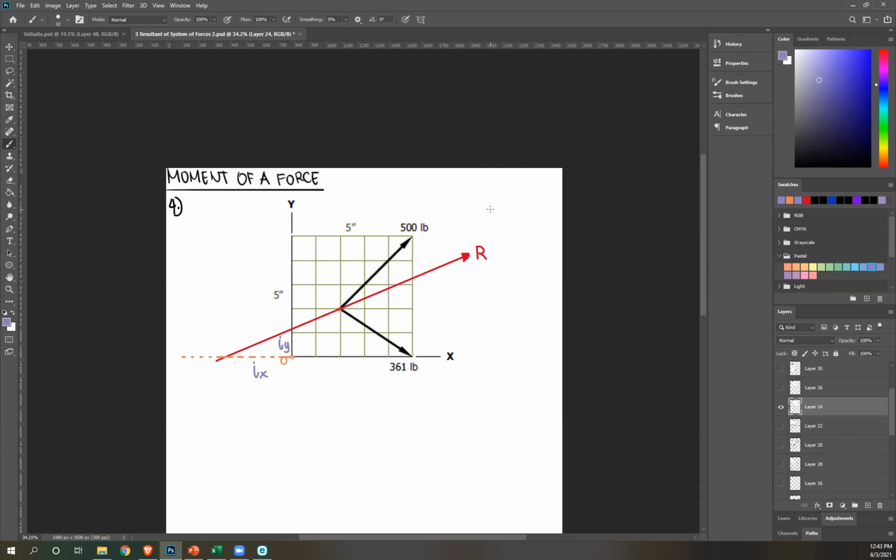Okay? So let's say this is your R. Component of R would be here. If I place it here, this is your Rx. This is your Ry. Right? And then, considering my components here, let's say I take moment about O. Okay, this is O. Rx passes through that, so I'm left with Ry. So as long as I know Ry and the moment about O, Ry's perpendicular distance to O is Ix. So I can solve for Ix that way.